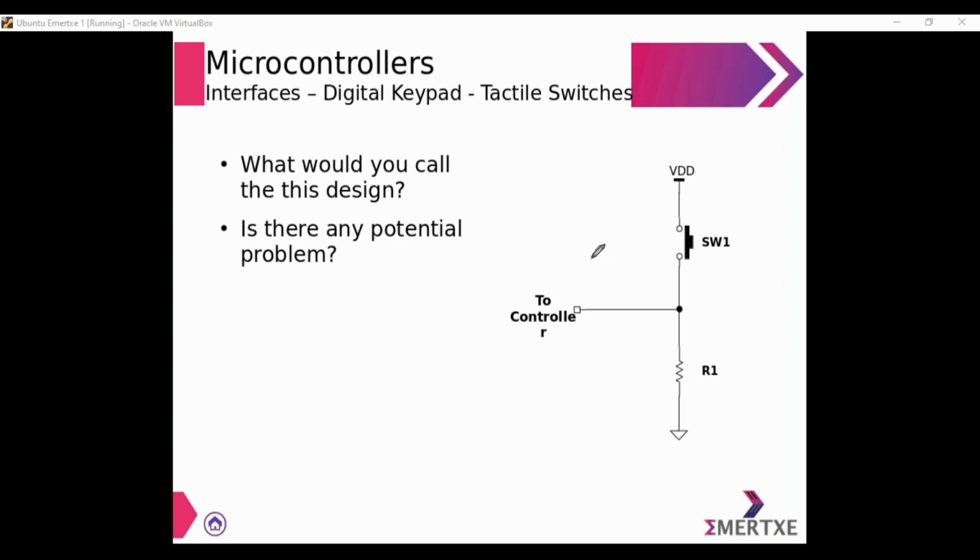Okay, yes, please wait. So I am taking a microcontroller here. It's in the reverse state. So if I am not pressing the switch, the switch is open, what are you going to read at the pin of the microcontroller? If the switch has been open, current from the microcontroller is flowing to the ground. So I should be able to read a 0 at the pin of the microcontroller, correct?